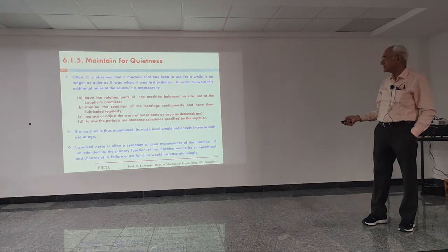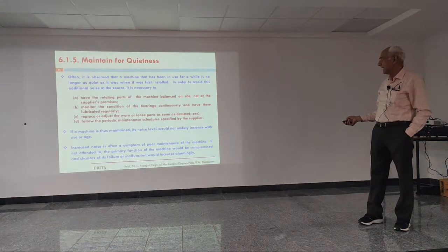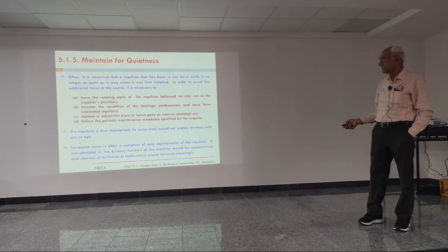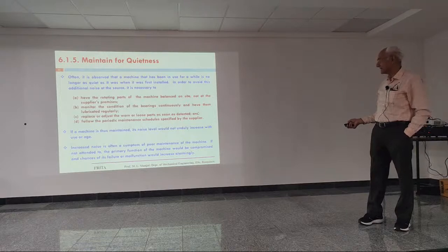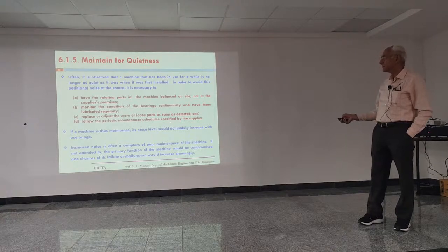Monitor the condition of the bearings continuously and have them lubricated regularly. Replace or adjust the worn or loose parts as soon as detected. And finally, follow the periodic maintenance schedule specified by the supplier. So this is all necessary.